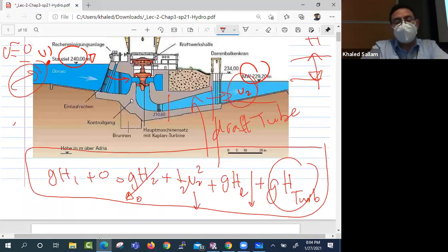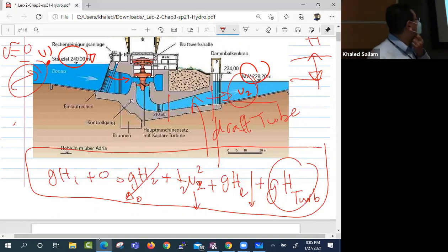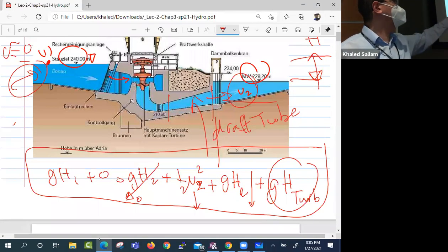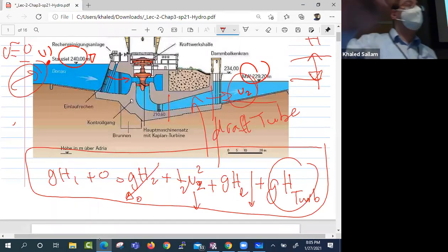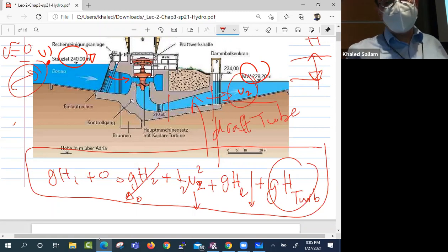But then this is your Bernoulli equation, right? So it's very clear why you want to slow down your V2. Not just because of the Bernoulli equation, but also because if the V2 at the exit is very large, that can erode your bed, a problem too. Okay, but one of you shouldn't be happy. One of you should question this equation. Something should make you uneasy about this.